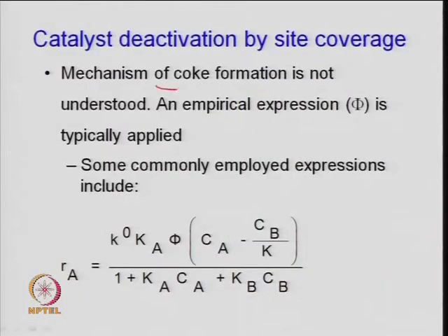So, deactivation by site coverage, which I have shown, because the coke formation mechanism is very difficult to understand, right. So, this is not well known, so we write it in the form of an empirical correlation. So, as I said, minus dA by dt, so that is my phi deactivation function, right. So, some commonly employed expressions, if you look at, define a kind of deactivation function which is related to coke formation, right.